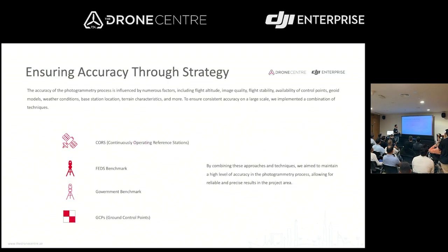in this project. To achieve this accuracy, we use four orders. Zero order is the control data from the government, which gives you good accuracy. After this control data, we establish our fixed benchmarks. Around each area, we have 3 benchmarks, and we compare our benchmarks later with the government benchmarks, which we have from the municipality. Later, during our flight, we use ground control points. Our ground control points, you can see here, are like a marker, like a sheet. Also, we use natural markers here.